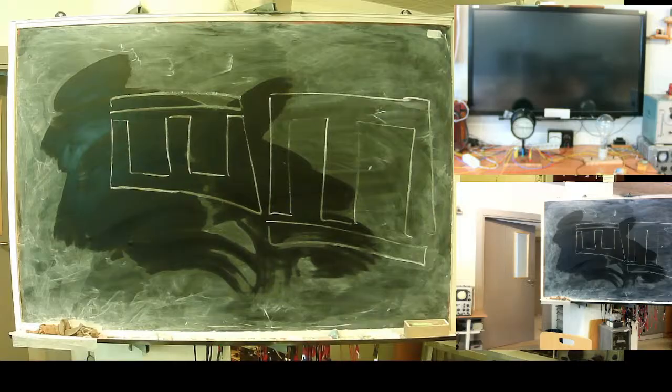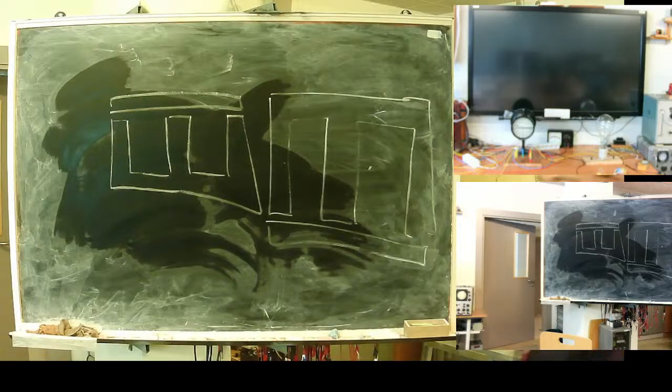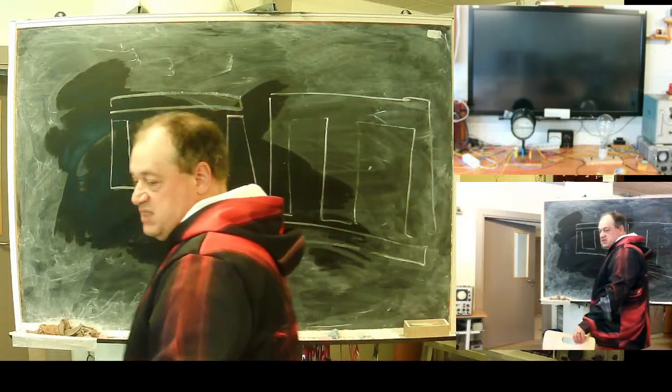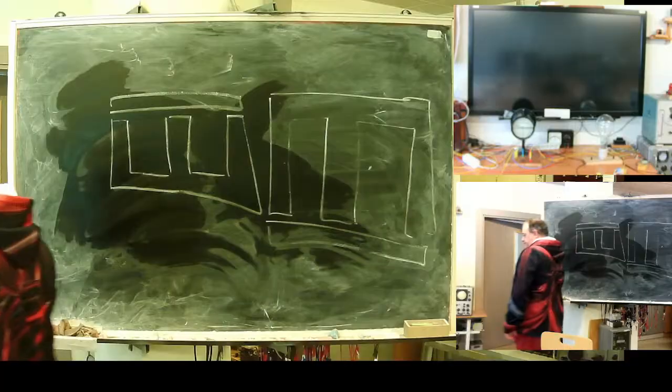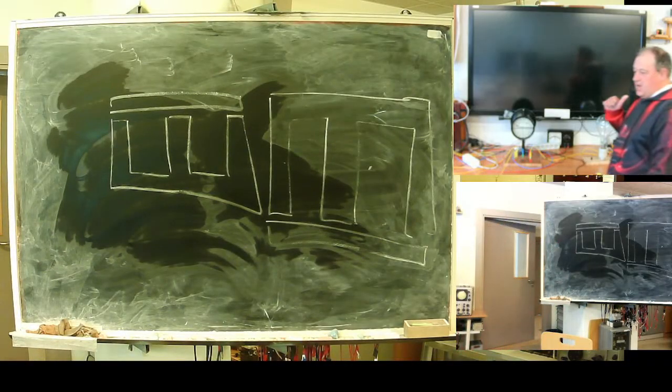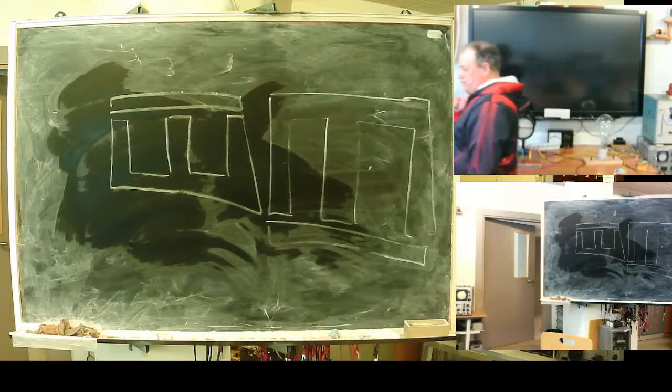Some manufacturers do what? They immerse the transformer in a kind of epoxy resin to make them solid, so to make them less sensitive to vibration, more resistant to overcurrents. Such kinds of transformers are cheap in manufacturing.